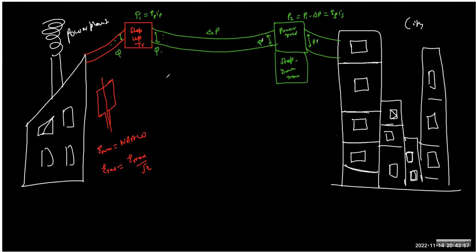So when you try to write the power relation between primary and secondary, you have to compensate for the loss. If the question says that there is some loss, subtract the loss, then write the power relation of the secondary. The ES will follow only this relation, NS by NP into EP. For this, we do not need the power relation.